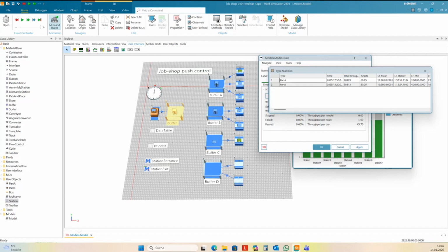Side note: if using the entrance control to set the process time, you need to initialize the process time within the init method. Otherwise, the simulation run might not be reproducible.